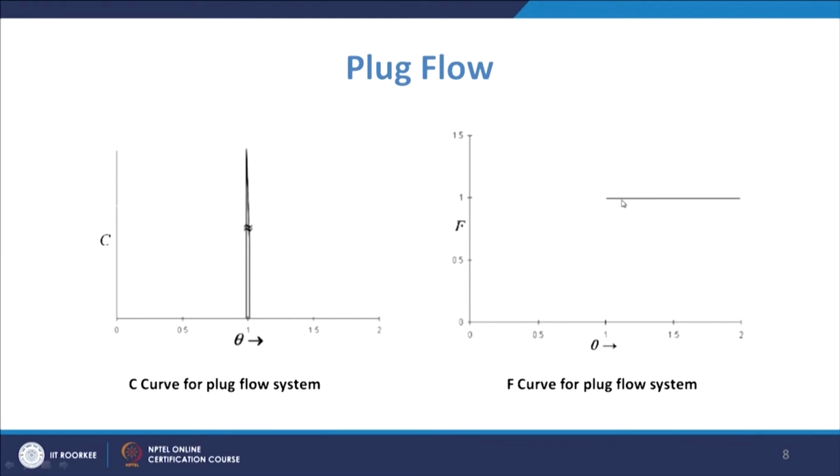So, basically tracer is continuously being put in, and all the tracer is flowing. It will stay together in the tundish for the theoretical mean residence time period, and after that they will start exiting. Once they start exiting, the concentration does not gradually increase; it directly reaches the full value. They are all coming out, so the dimensionless concentration is 1 itself.